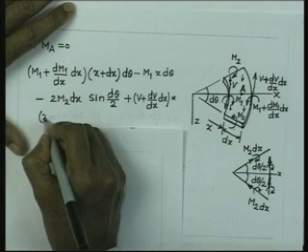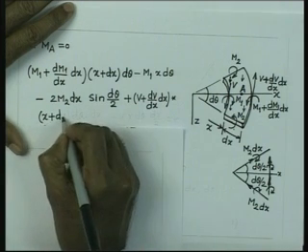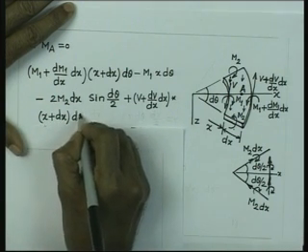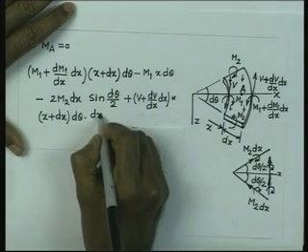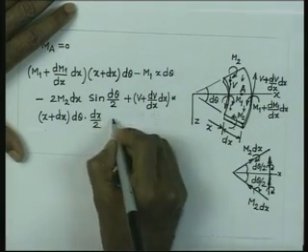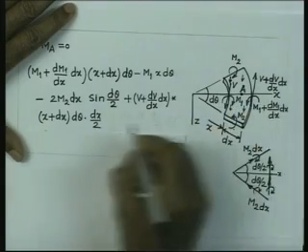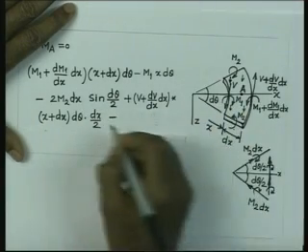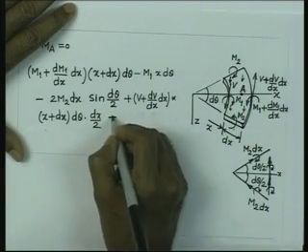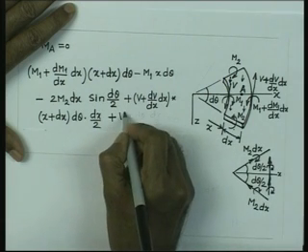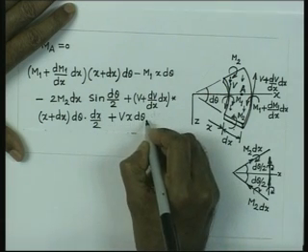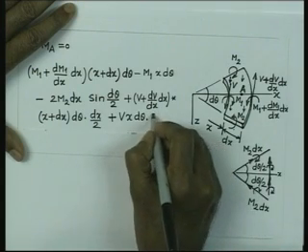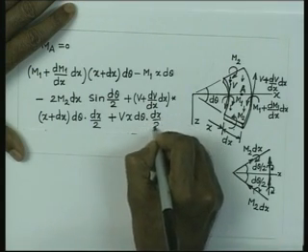So, into x plus dx into d theta, and the moment arm is dx by 2. Similarly, for this one it is V, and it is producing a moment in the same sense as this one. Therefore, V x d theta is the total force due to the shear force, and its moment arm is dx by 2.